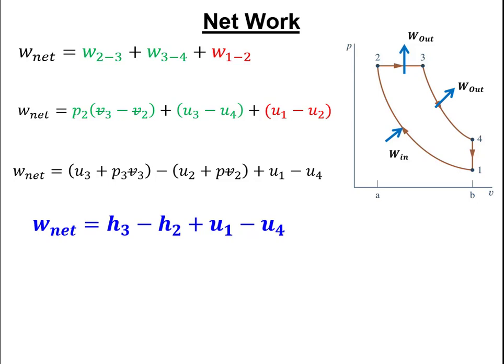Now we should remember how to derive this equation, but as a tricky shorthand, what I like to remember is that the equations for the diesel cycle look the same as the Otto cycle, except my two states that are on the horizontal line become enthalpies, and the specific enthalpy is h. So if it's on the horizontal line, it gets h instead of u. And that's nice because horizontal starts with the letter h.